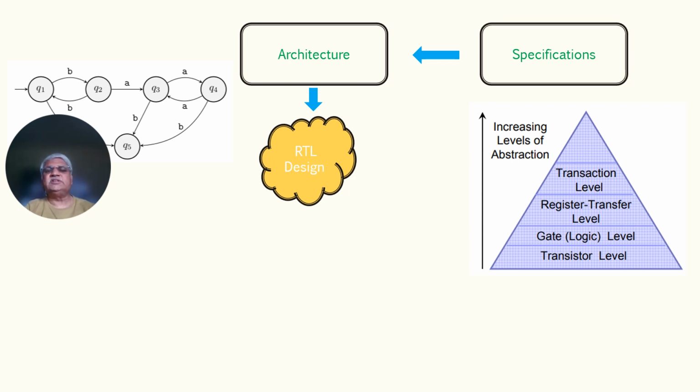There should not be any non-synthesizable blocks. Assume that you wanted to create some logic which is actually not synthesizable through the existing technology cells. Then it is difficult to finally realize. And there should not be undriven nets. That means you have created some logic and it is not going anywhere in the design.